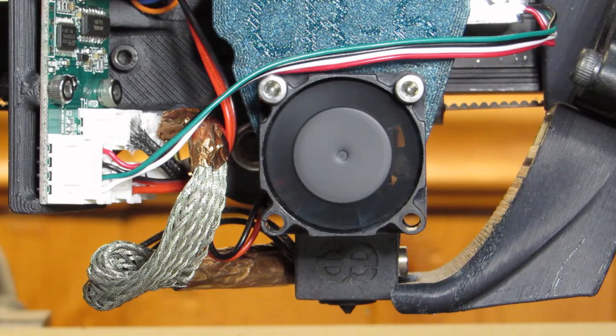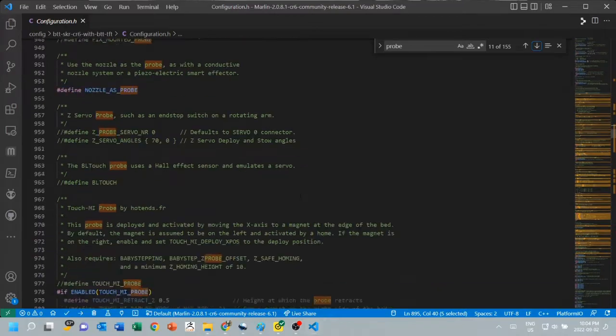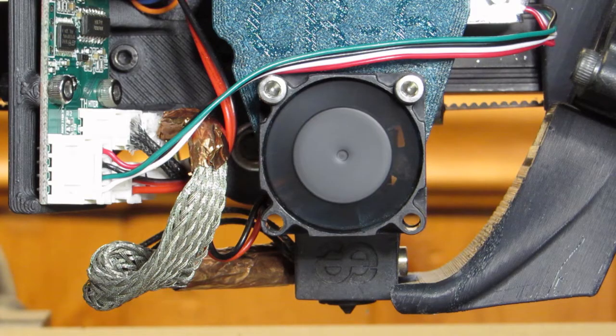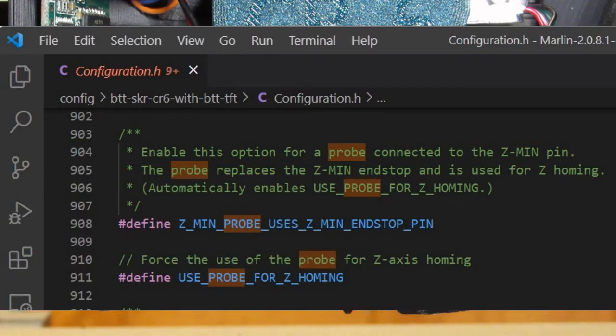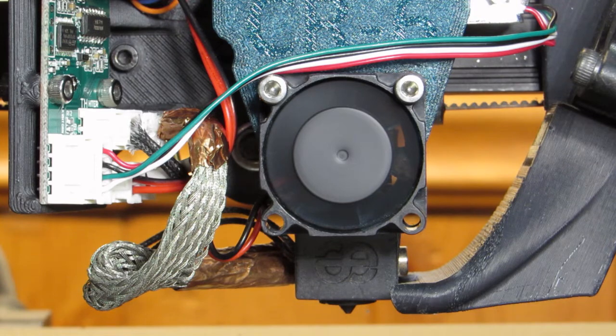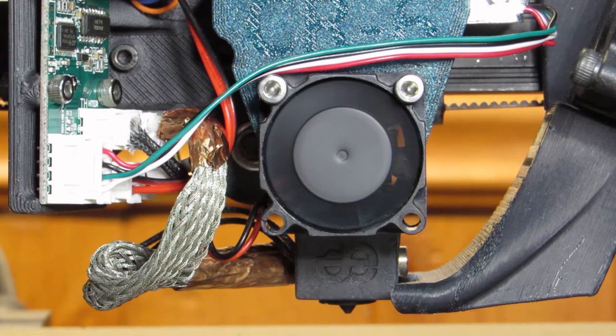I, the probe, have now detected Z equals 0 right here. And Marlin is programmed, according to the machine it's been configured for, to know how the bed is actually detected, with what type of probe, because each probe has its issues and vulnerabilities and expectations of it.